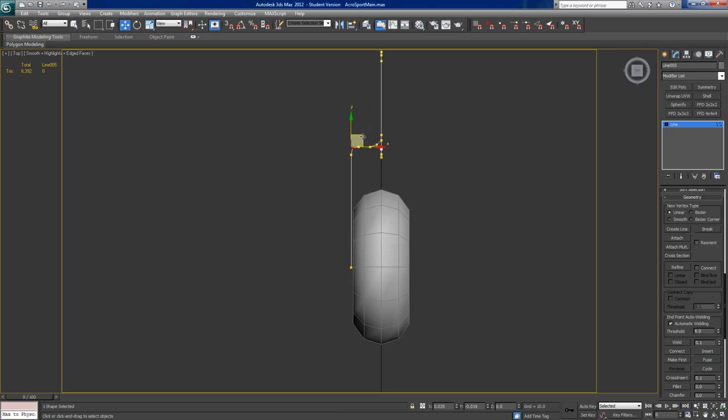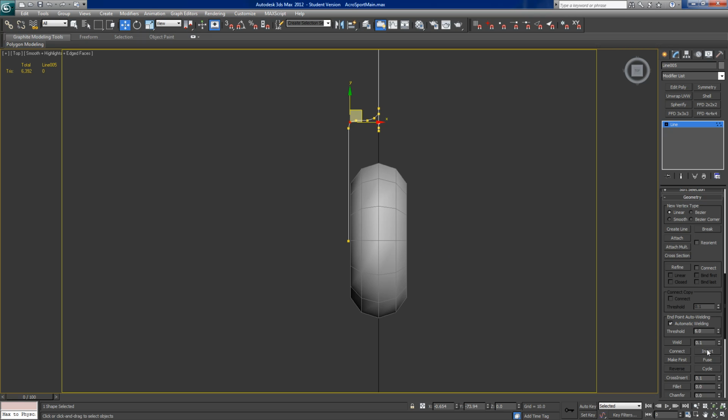I'll go back to this guy, round him off, pull the corner in, and since I can insert, I'm going to insert another bend here. So I'm just clicking once, pulling away, and then this drags out. I'm going to just right click, and then that'll go away.